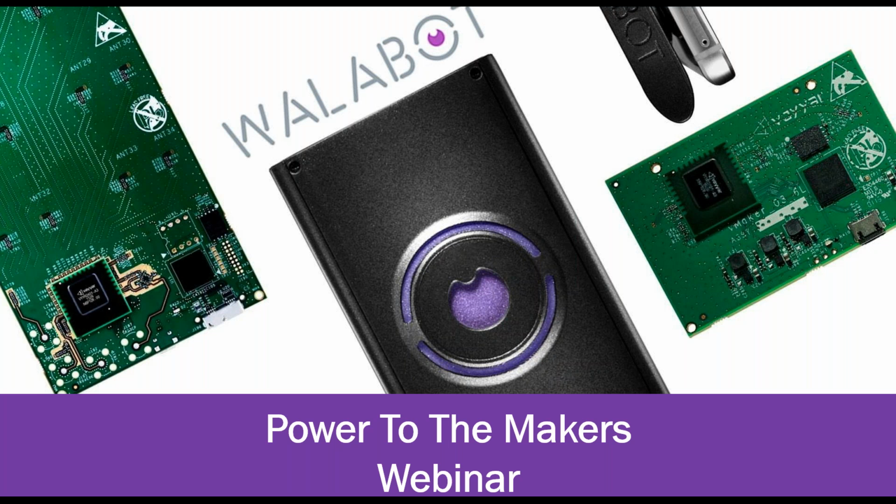What type of calibration would I use to be able to detect multiple targets at, say, up to 8 meters? There aren't types of calibrations; there's only one type. The main thing is to place the Walabot as static as you can and leave the arena empty, then calibrate, which means calling the triggering function enough times for the calibration to complete. Make sure the arena is totally empty, so that each object that enters the arena after that will be detected clearly.